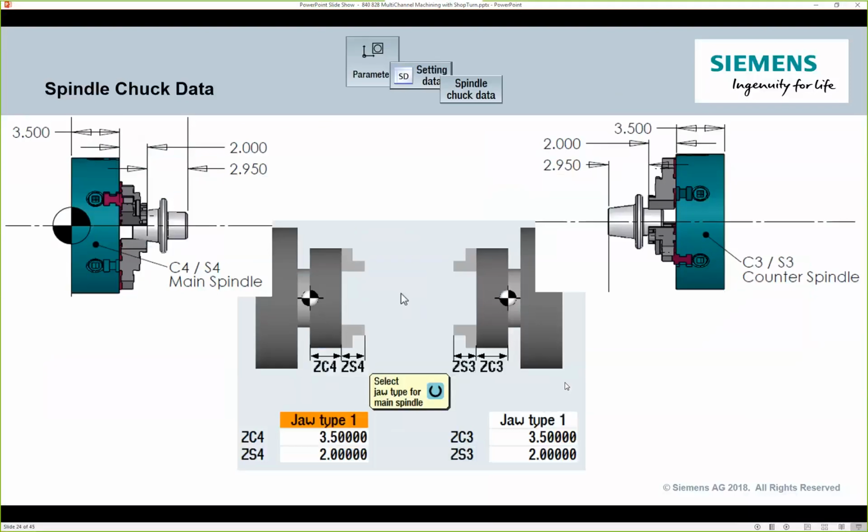So now that we started looking at how we move our machine around a little bit, and some of the unique functions that came up with this type of technology, now let's look at how the system builds. We're going to have to do the same steps we did in that earlier webinar, which is describing our work holding. And it's probably even more important with this type of technology, because you've got a lot of stuff going on. You now have two separate turrets, channels, and programs, all addressing the same offsets. So I would strongly suggest adopting this type of method.